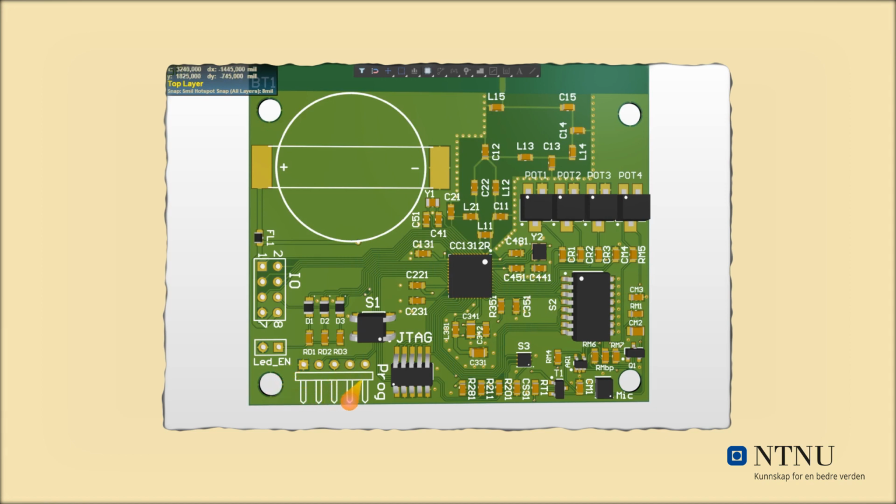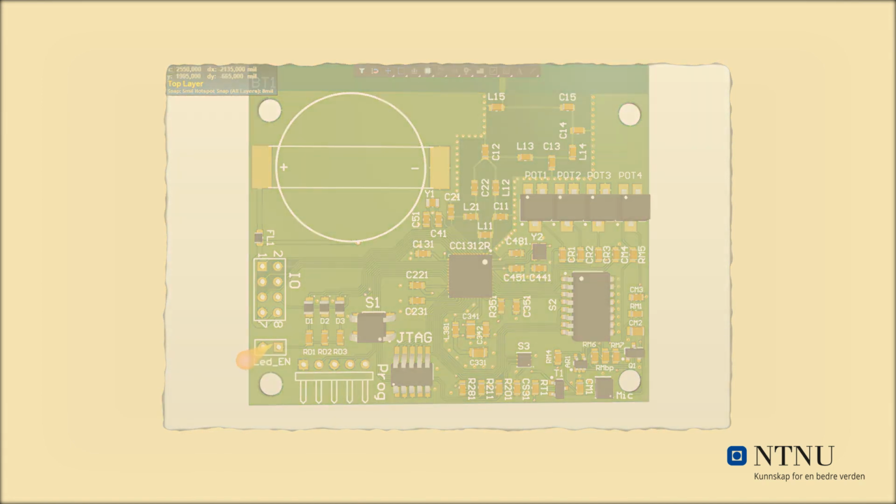The pairing port is used to pair the node to the master node's network. This one is custom-made and has a detection circuit on the master node side. It can detect if it is inserted the wrong way and protect both units. It also has a standard JTAG interface, which uses the same pinouts as the Launchpad series. And we have a few debug LEDs here, which are enabled by this pin here. You just short the header.